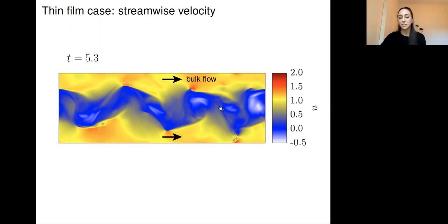So the density difference is 40 to 1, and it's stopping the flow moving. Part of all this aerodynamic study is really understanding this liquid film almost like a membrane. For all intents and purposes, all the analysis that I did was as if it was a solid surface or a membrane, so I can pick out the interface exactly and integrate the pressure over that. And that's sort of what we see coming out here.